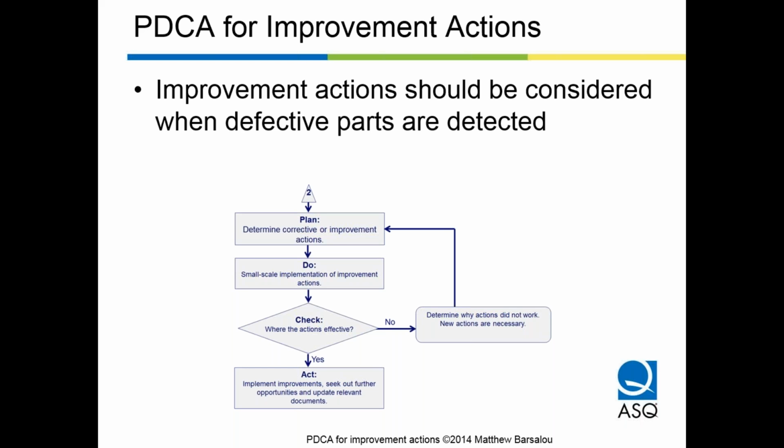When I do an evaluation of a failed part, I often ask my colleagues when they plan it with me, what will we learn? I don't want to have an experiment where if the part passes, we don't learn anything, and if it fails, we don't learn anything. In one of those two scenarios, we should at least learn something, even if it's just hypothesis was wrong. Also valuable information.